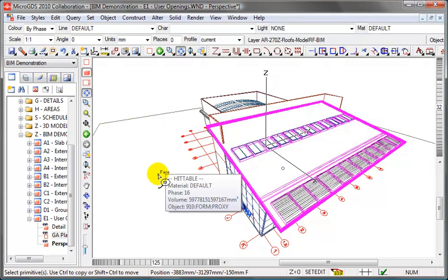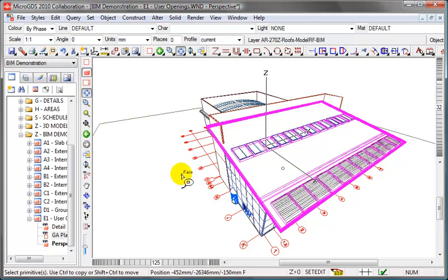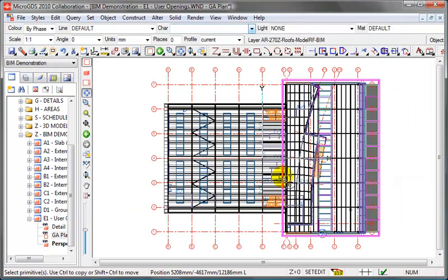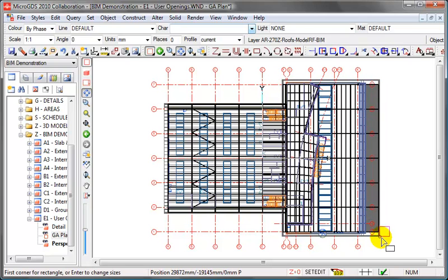And we need to now create ourselves a cutter primitive. The cutter primitive is what is going to remove the upper part of this wall after we've carried out a few more, shall we say, interesting steps. So we'll switch to our 2D plan view and set the Z=0 lock on to make sure that the rectangle's been drawn from a point snap on the two opposite corners of the roof extent itself.